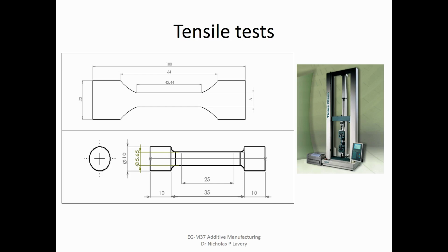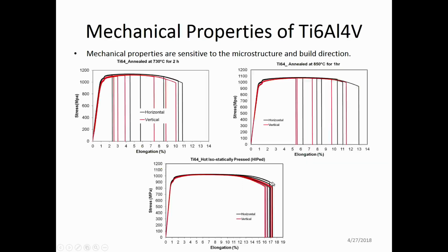And you've got a lot of flexibility in additive to be able to make those tensile bars. You might not have so much flexibility in other processes, and you're going to have to cut out big sections. So you can net shape them. Are you going to have a cylindrical format, a round tensile test bar, or are you going to have a net shape rectangular dog bone type test bar? And what sort of dimensions are you going to use to accurately capture the real properties of the material? So that's something that you need to think about very carefully.